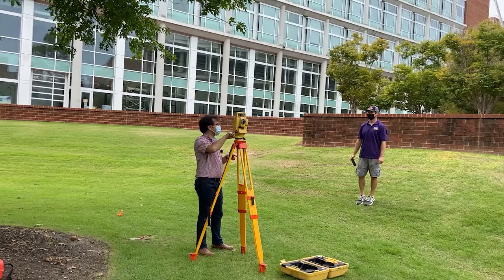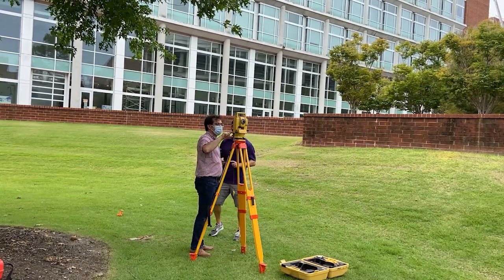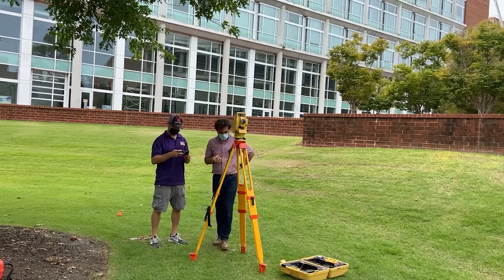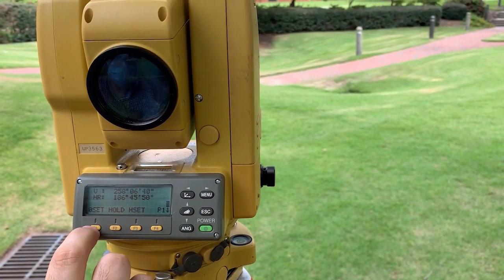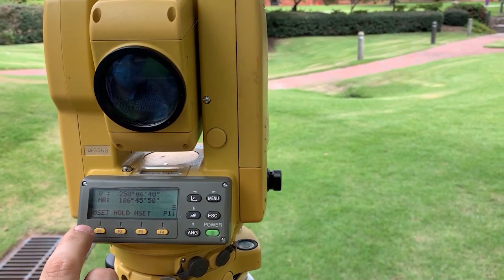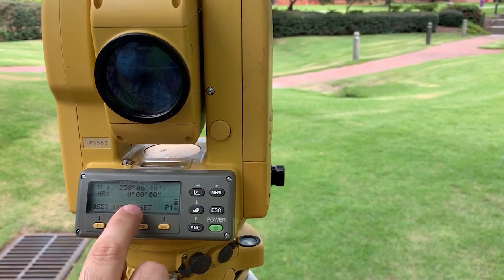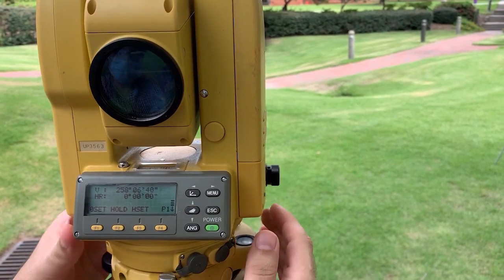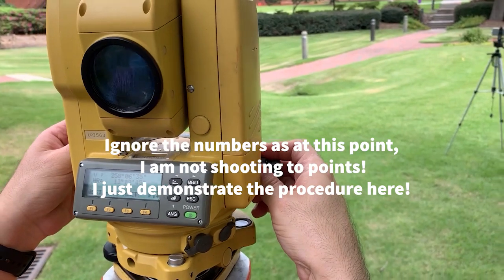Let's have a closer look and review the procedure one more time. Look through the total station screen. Now you press angle. Now set it to 0. Do you see F1, 0 set? Yes, it sets to 0. Do you see the horizontal angle is 0? And then you keep rotating, and you see that it changes.